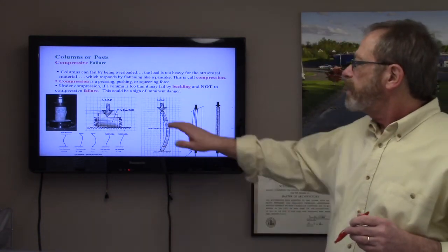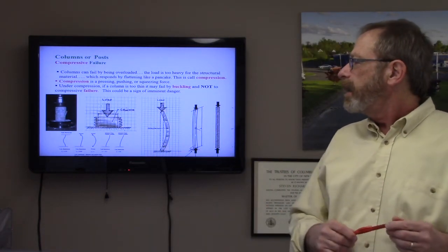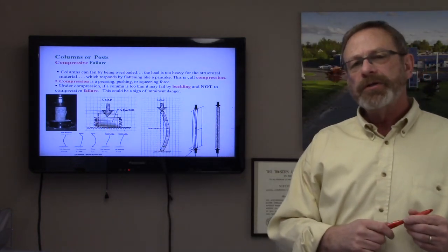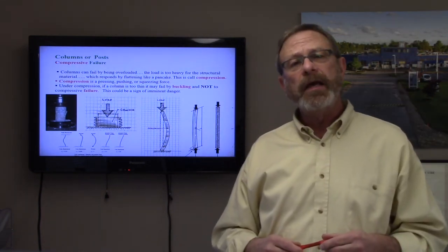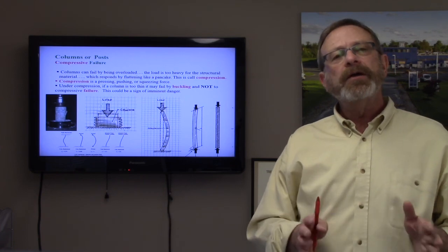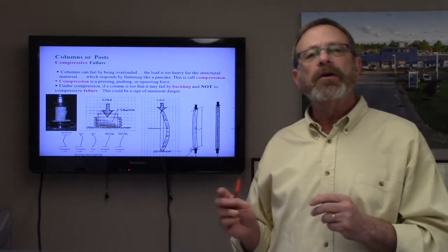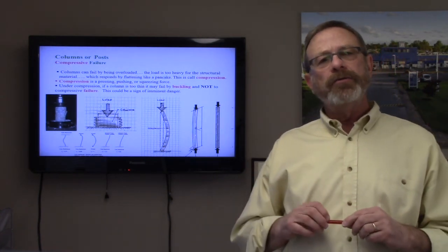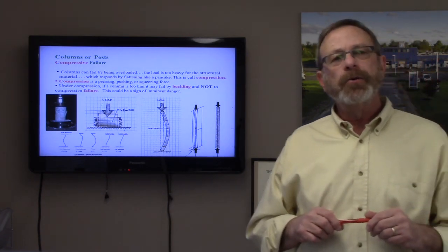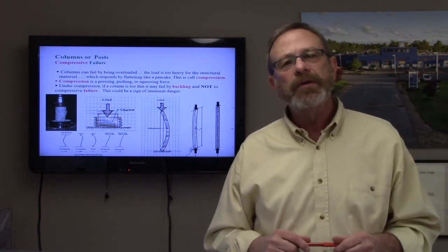In this case, we can see a test of concrete strength being performed on the left by a lab test that was done on some concrete poured on a real job and tested after 28 days, which is when concrete achieves its full strength, so that we make sure that the contractor did not shortchange the owner with the formulation that the engineer had specified to meet the requirements of the loads of the structure. In other words, some unscrupulous contractors might take shortcuts and therefore jeopardize the structure of the building. We don't ever want to see that happen.